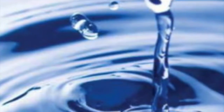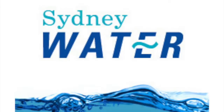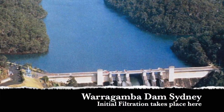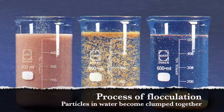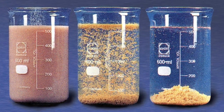There are 7 main steps that Sydney Water takes to sanitise and filter water, information taken from Sydney Water and Hunter Valley Water. The first step is the filtration of the water, which comes from a dam or river flows or is pumped into the water filtration plant through pipes. The second is the water goes through screens to remove things like leaves or twigs. 3. Flocculation. Chemicals are added to make very small particles clump together. These particles are called floc.